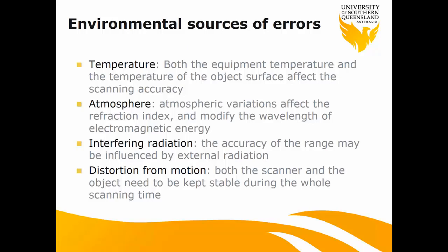Temperature. The instrument temperature and also the object surface temperature affect the scanning accuracy. Atmosphere. That will affect the refractive index. We know this from the EDM principle. We know the temperature and other factors will affect this refractive index, so that certainly will affect the range measurement accuracy.